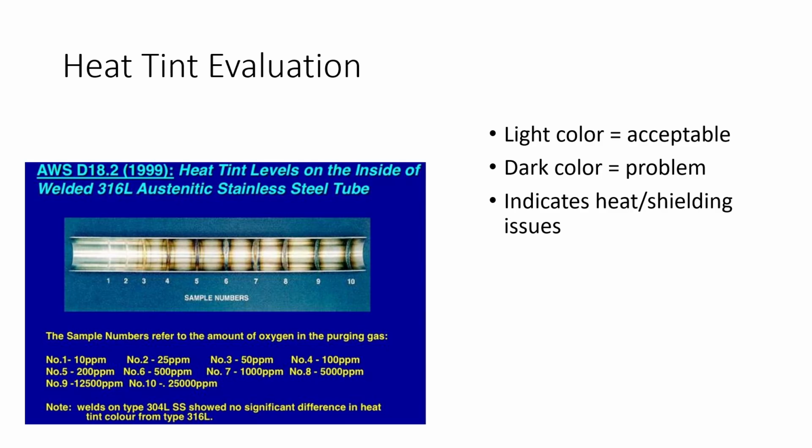Darker colors, grays, can indicate that we got it way too hot or we got shielding issues. We could do a deep dive into this and talk about it for a while. There are people who have put this together that are metallurgists and engineers, and it gives you a pretty good indication on whether you deposited the weld metal right, or if you damaged the base material and the weld material that you just put into that weld joint.